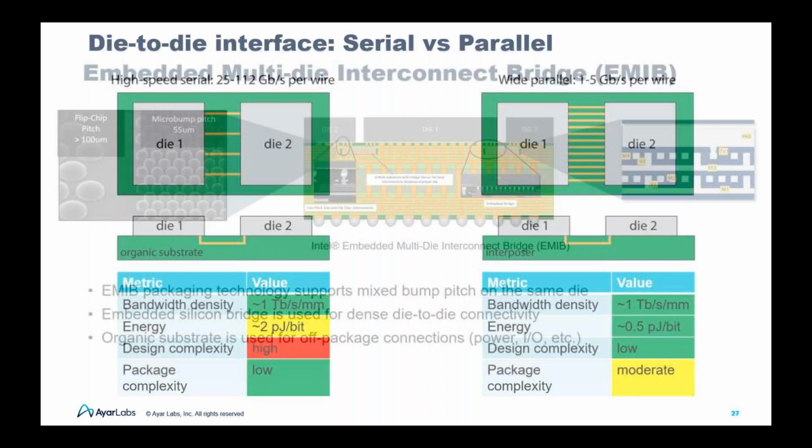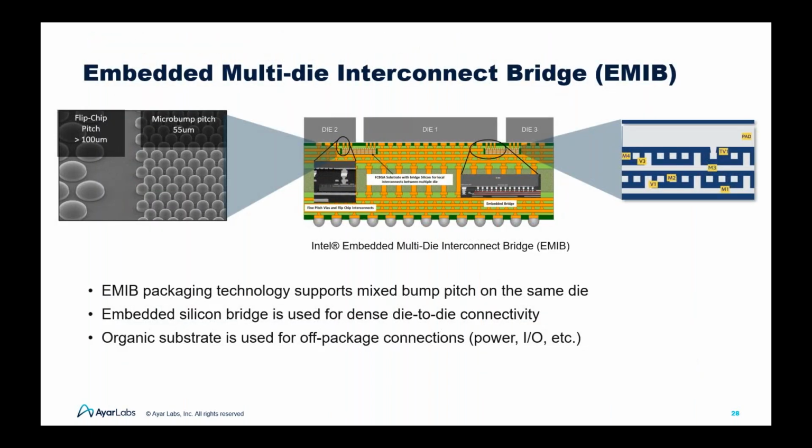And basically, this is the structure that we picked. We are using EMIB from Intel for integration and AIB over it. I think if this is a slide, if someone is interested, what is AIB? AIB is just a piece of silicon underneath, inside the package between the two dies, and you get basically the 50 micrometer micro bump pitch connection to the die, and all silicon goes up. I think this is something that Intel wants.